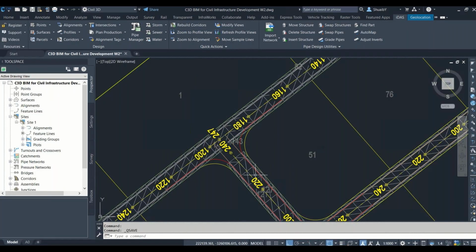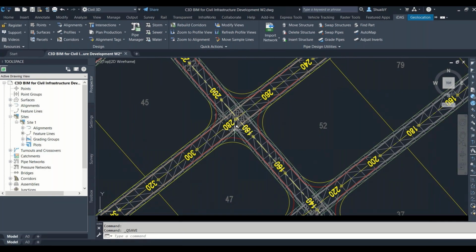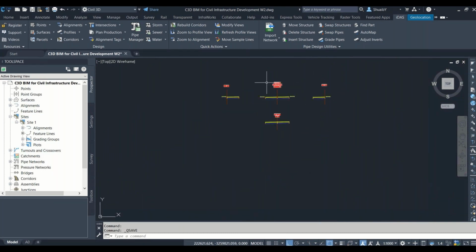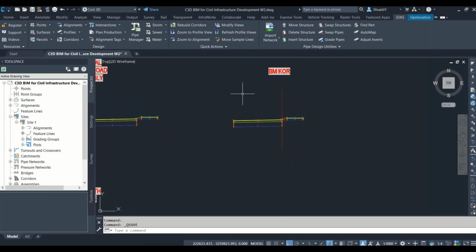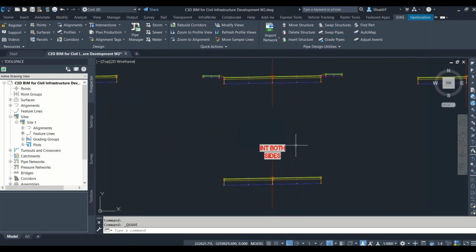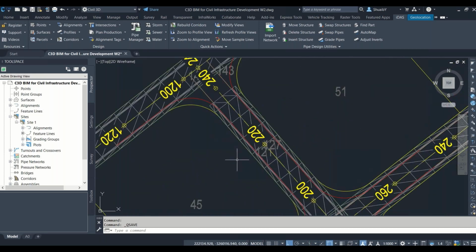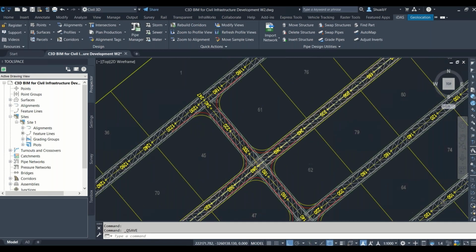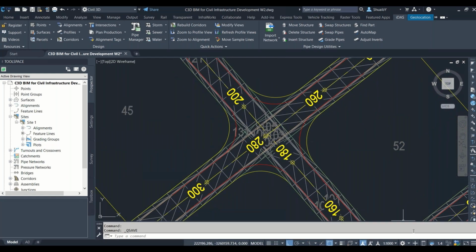So now that we do know that, let us go and have a look at this four-way intersection, right? You can see I've created assemblies. This stays the same in Civil 3D, where you will need to create your kerb returns and so on and so forth, all right? So that when you are using the Autodesk wizard for the intersection, you have your assemblies created. Okay, so let us just do maybe this one here.